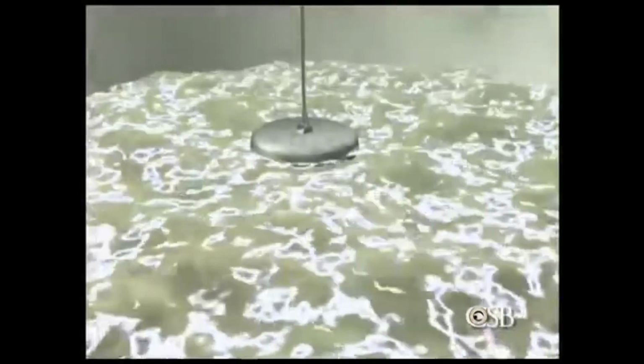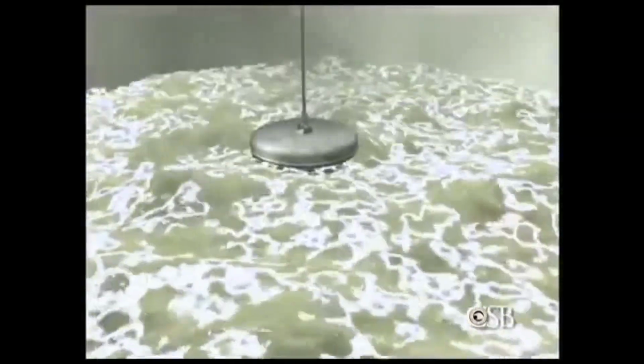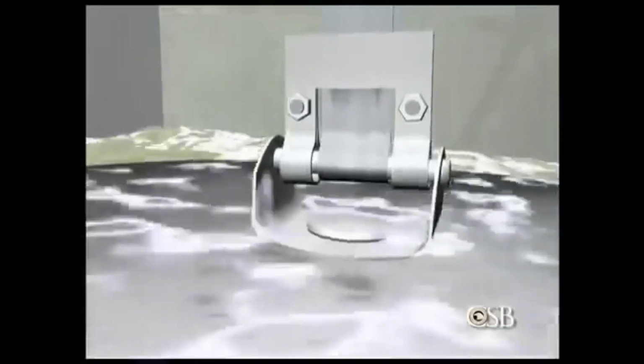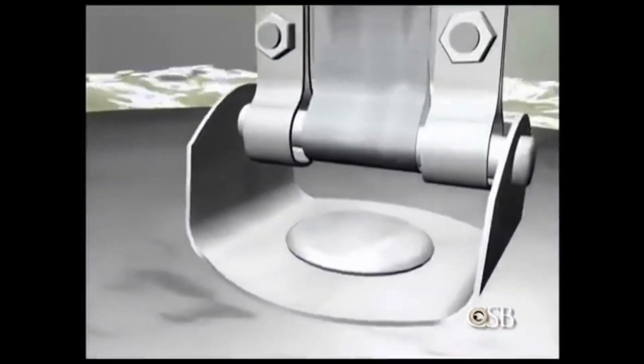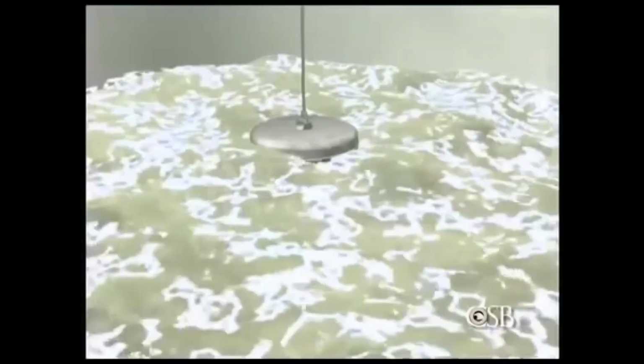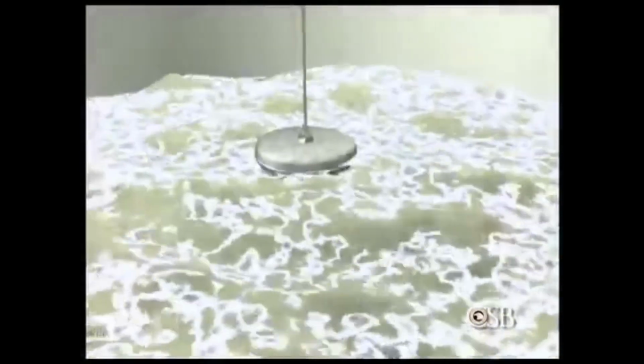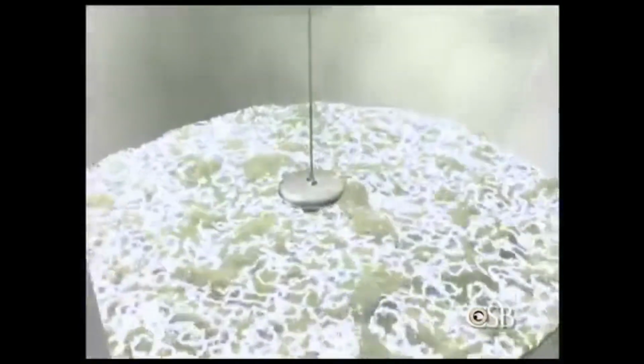Because VM&P naphtha is a poor conductor of electricity, the static charge accumulated faster than it could dissipate, even though the tank itself was grounded. A lot of common flammable liquids are particularly susceptible to ignition by static sparks. At normal temperatures inside a storage tank, they can produce the optimal amount of vapor to fuel an explosion.